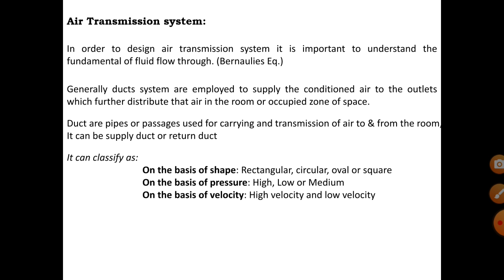That is called the phenomenon of discoloration of the wall, if your duct surface is not properly insulated. Because there would be a transfer of heat between this cool air at 14 degrees Celsius inside the duct and the air outside the duct at 35 degrees Celsius. This outside air reaches its DPT and starts condensing; the water vapor condenses. So that is also one important thing: the duct must be insulated.